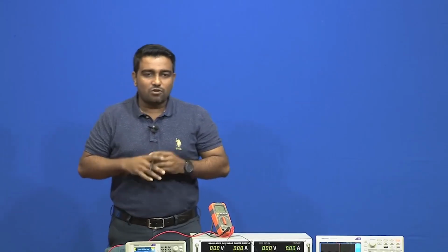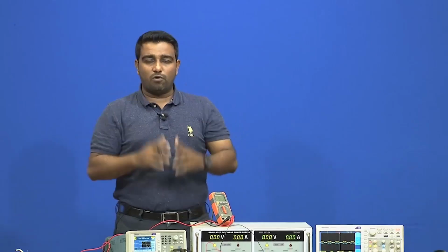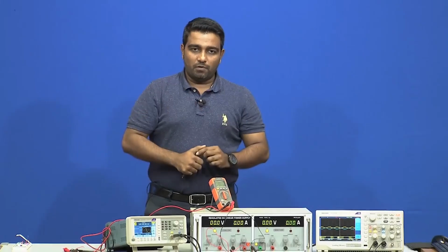But what we saw in the experiment is that even though there is infinite gain, right now we had a gain which is limited, about 10, but we can always increase the gain. Even if there is infinite gain, the output cannot reach an infinite value, but is limited by the bias voltage. That means one op amp cannot generate that much power that the whole institute requires. So, always remember, do not get confused that infinite gain means we can have infinite voltage at the output. No, it depends on how much supply you have given to the operational amplifier, alright.